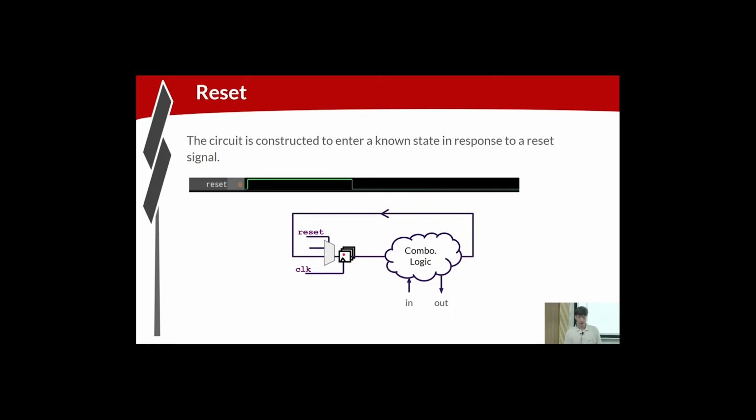It's not necessary to reset every flip-flop in the circuit. Many design teams will use a methodology where every flip-flop is a reset flip-flop. If you're designing with FPGAs, on some FPGAs, all the flip-flops have reset support. But it's not necessary to drive reset to every flip-flop. And as we go through, you'll see how to think and reason about where we need reset and where we don't.